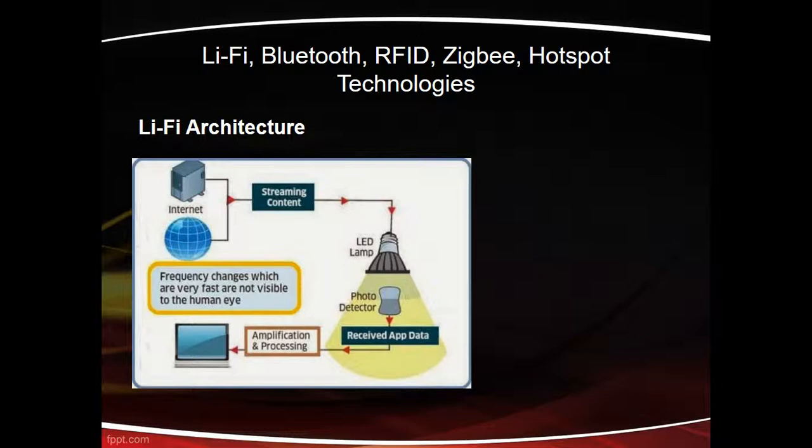This makes binary logic. For example, when the LED is on, it transmits 1, and when the LED is off, it transmits 0. During transmission, the optical signal is detected and received by a solid state photodiode at the user equipment receiver. So the photodiode is used for receiving, and the Li-Fi system utilizes a controller to transmit data along with controlling the LED light bulb. That controller also controls and varies the rate at which the LED switches on and off, which is a critical component in data transmission with Li-Fi, because it controls the variation rate, right?